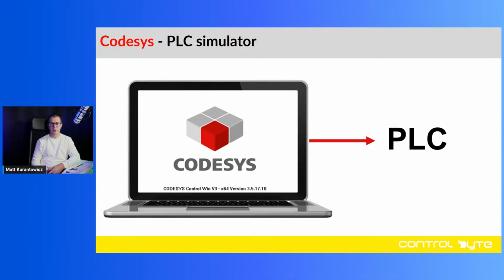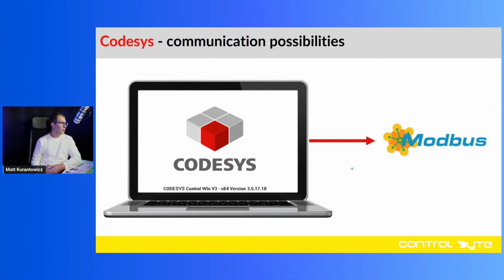We use that software to program our projects and also to simulate PLCs. You need only your computer to start with programming. You can just download Codesys for free and enable a PLC simulator. Also, you can create communication between your PC and external devices. You can use the Modbus protocol. You can just install a PLC simulator.